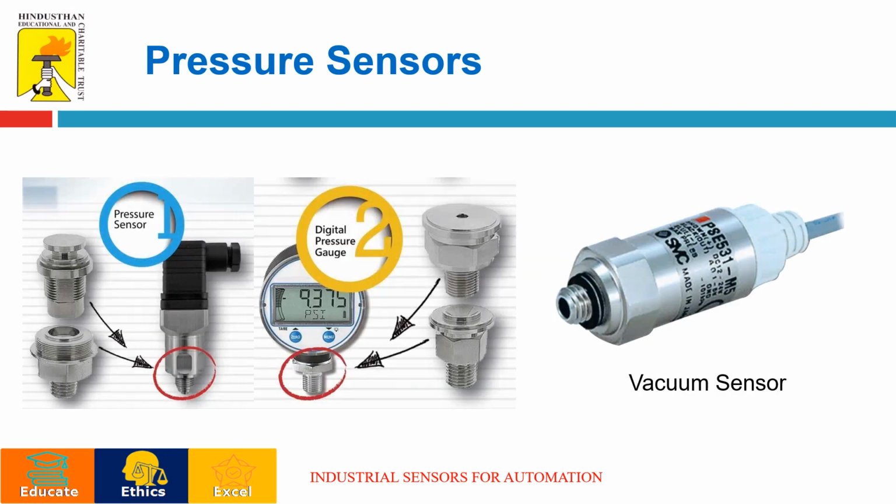This is the representation of the vacuum sensor, and you can see the digital pressure gauge, which shows the pressure, and the sensor where the signals are converted to a current loop of 4 to 20 milliamperes. Based upon the variations from 4 to 20 milliamperes, you can sense the pressure variations at that particular point.